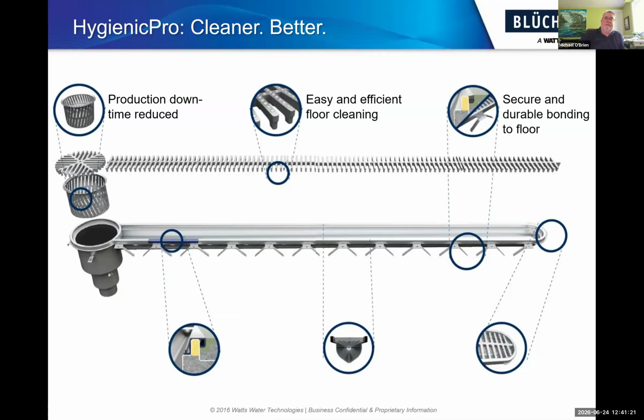And you can see all the way along the trench drain on both sides are these anchor tabs. They have a flat surface where they can use some rod to position and level the channel and hold it in place for the concrete pour. And then these tabs fold down in opposing directions. They run the full length, and they're integral. They're not welded on. They're actually formed as part of the channel when that piece of metal is stamped.